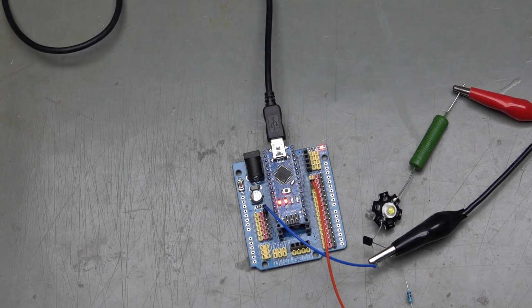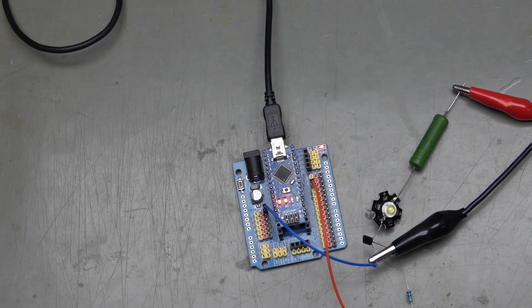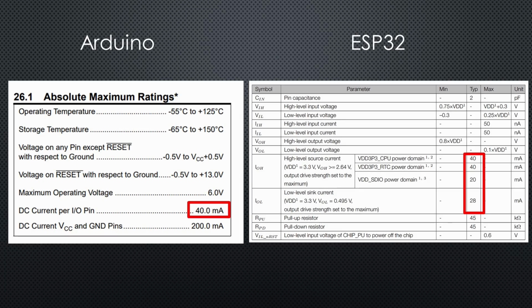To understand where we have to choose an NPN or where a PNP transistor, we can build a simple setup. An Arduino which has to switch a power LED. According to the datasheets, the Arduino or ESP pins only deliver milliampere, but our power LED consumes much more. Fortunately, we learned before that transistors amplify signals. The BJTs in particular amplify current, exactly what we need for this case.